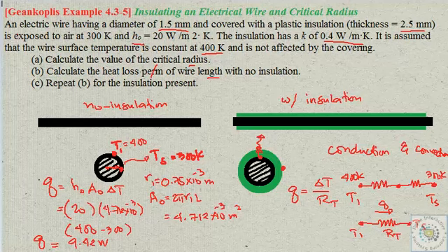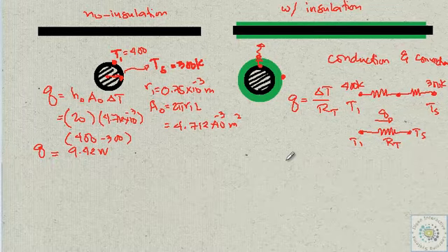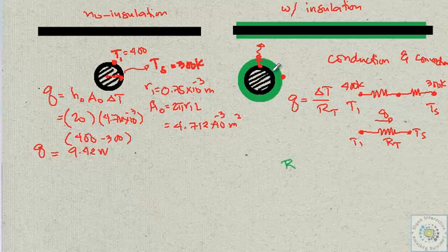So let us first calculate the R given by this insulation. Let's call this RA, and this one RB, the resistance offered by the air. RA, since it's a cylindrical wall, will simply be the thickness of that wall over the conductivity of that insulation, K, times the area log mean. How do you compute the area? Well, the area log mean here is for this insulation.